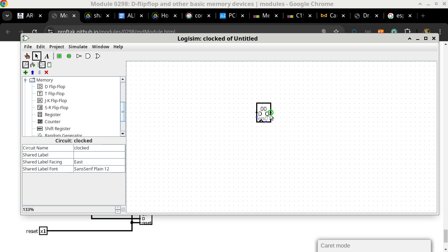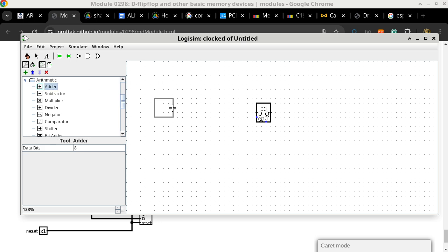So what we'll do is we are going to hook this up with an adder. So we go to arithmetic, get a little adder here, okay, because we're going to make a counter. So we look at the output, we use it to hook up to one of the inputs of the adder. Carry in, which is this pin here, is essentially K0, the way we described the adder.